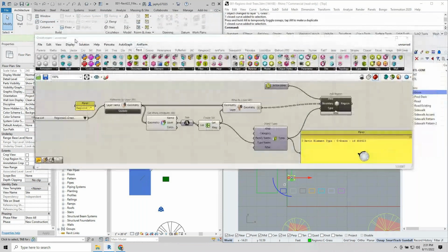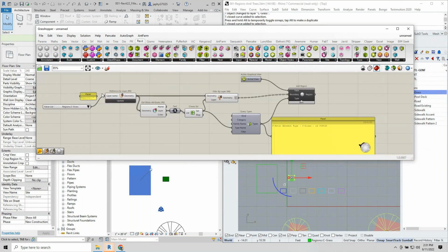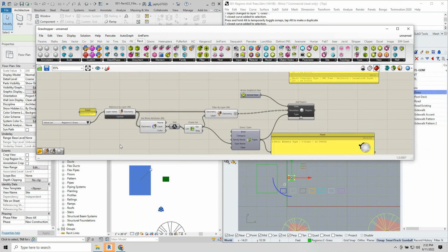Okay, here's a really good example of a contextual crash. Sometimes it's a soft crash. With Rhino.Inside.Revit, it's three programs working at one time. So you have your Revit, your Rhino, your Grasshopper, and Revit being a database opens up a transaction for everything you do, and occasionally it gets confused and loses context of which program is going on.